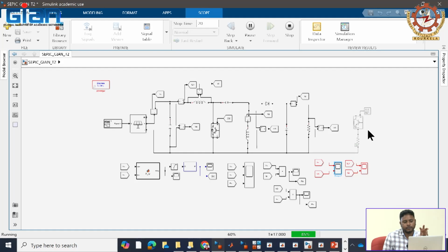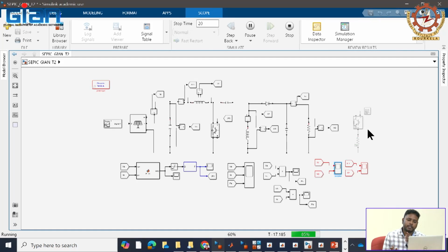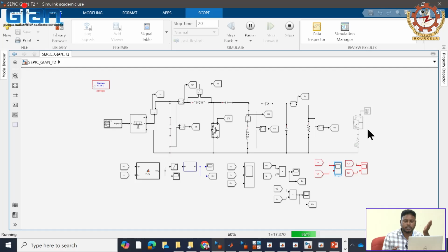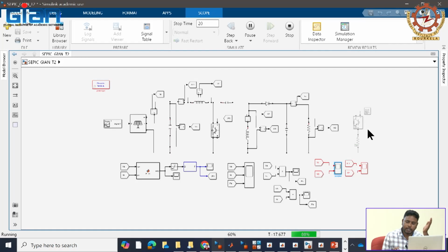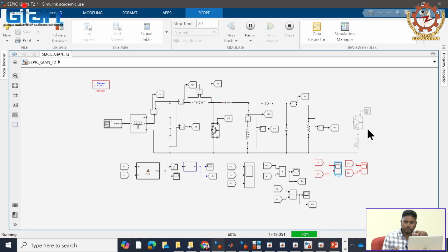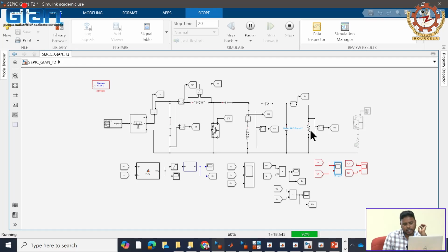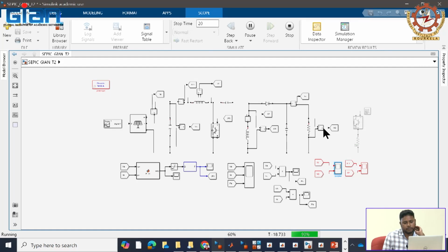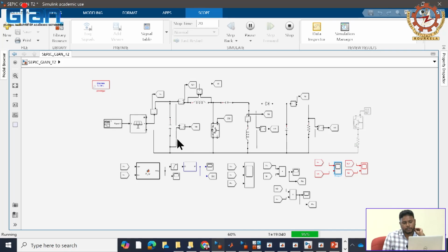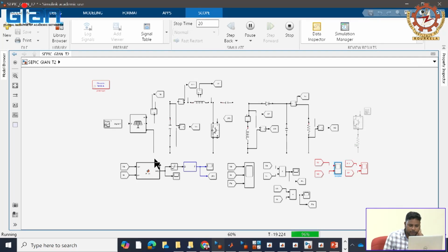So if I need 2 kilowatt but it is generating 2.5 kilowatt, how can I get 2 kilowatt? You can make it an off-MPPT, and use a controller to make constant power. Here I am using only a constant load of 4.9, but the voltage, current and power are all varying. If you want constant power, you have to use a controller and use this MPPT as an off-MPPT.